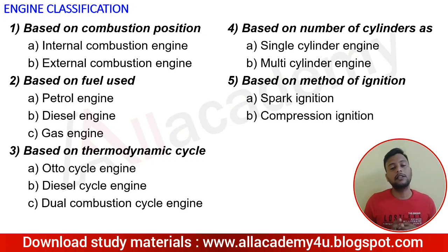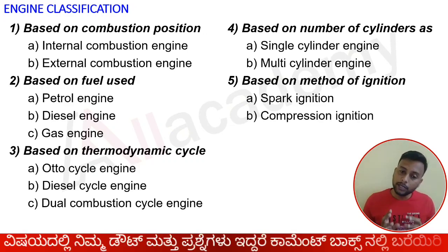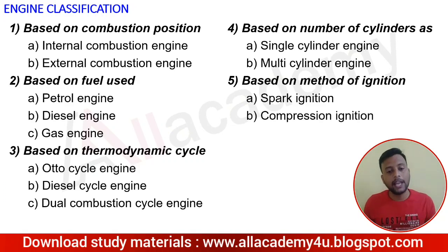So what happens in a diesel engine? The air-fuel mixture will not enter the cylinder. Only fresh air will enter the cylinder from the inlet valve, and after this air is compressed, the fuel is injected with the help of a fuel injector. That is, diesel is injected with the help of a fuel injector, and the combustion takes place due to the high compression, that is high pressure. So that is a compression ignition system.